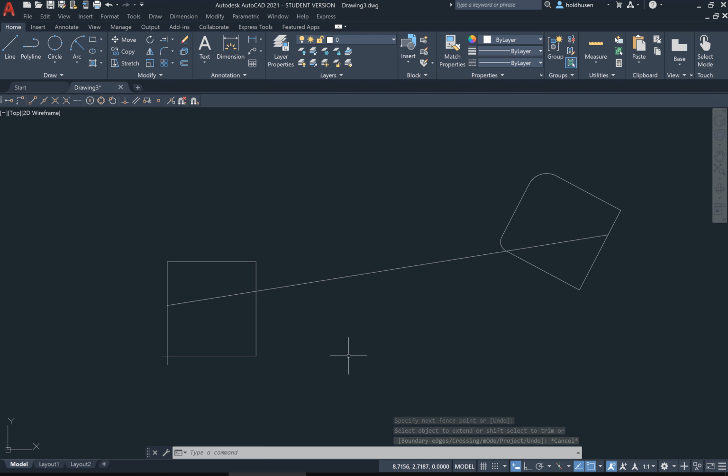Next one is polyline. Okay, so you think about the square that I created here. When I click on it, it's actually 4 lines. But I can turn it and kind of group those together in what we call a polyline. And that's under the modify feature here, right here, polyline. Now, notice I selected that line and went to polyline, and it says, hey, that's not a polyline. Do you want to turn it into one? And I can click yes.